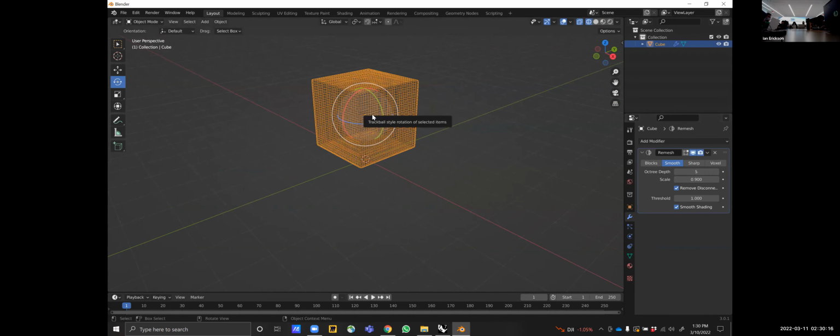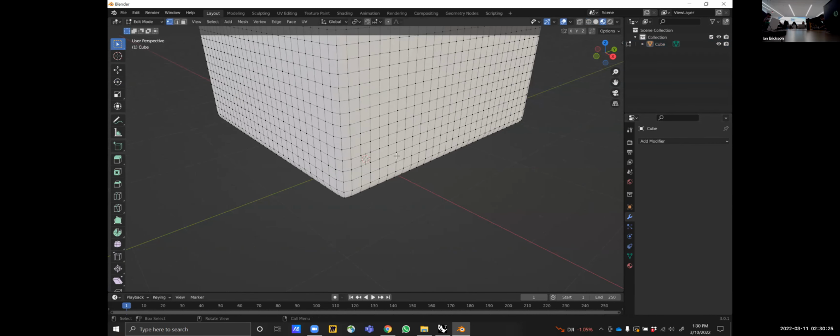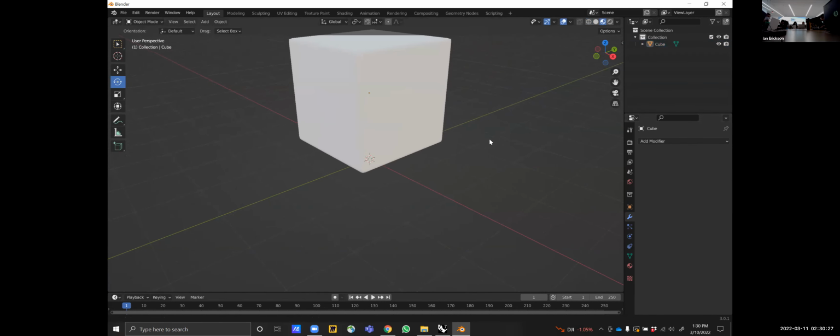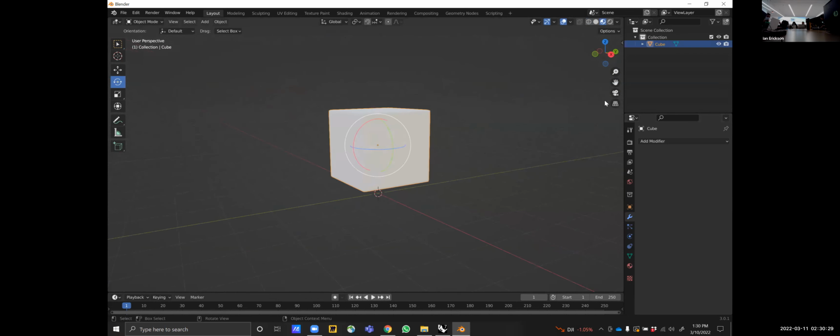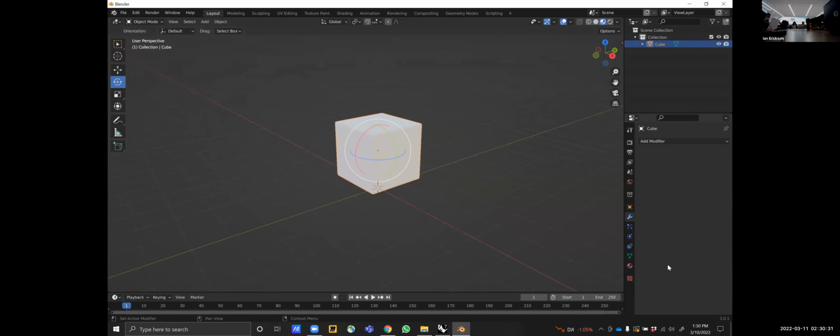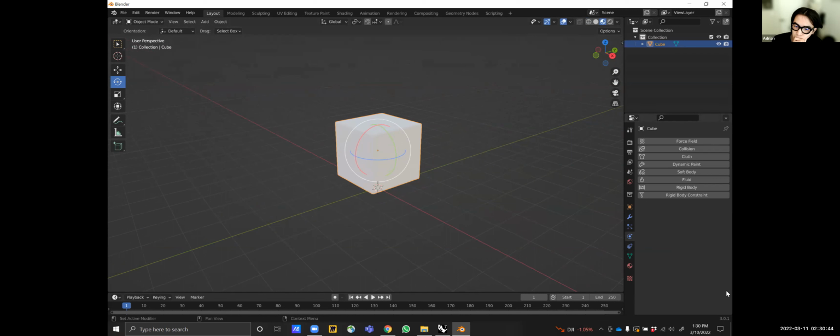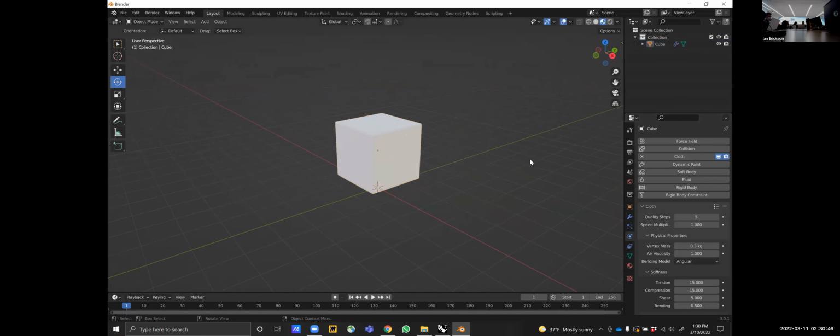And so once we've played around with all of those settings, we'll just apply that modifier, and we tab again. We'll see there's now a greater number of vertices. But now that we've prepared this geometry, we can just start to play around with simulation settings. And so we'll do that in the physics properties tab, which is the circle orbiting a circle that's just 2 beneath the wrench that we were looking at before. And we'll flip the cloth.